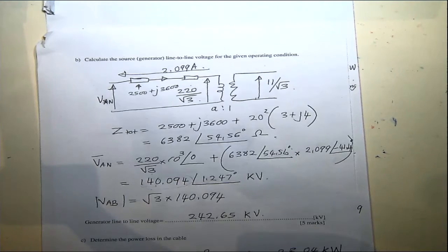If you say 220/11 kilovolt rated transformer, then you apply 220 here without any loading, you have 11 kilovolt here. It's no load. So here is 11, and then we neglect this one.